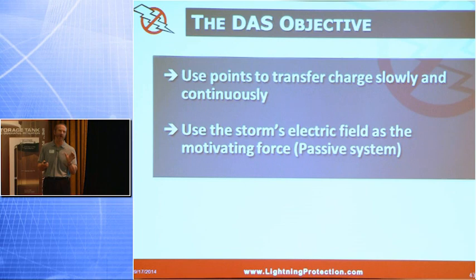You don't want to have too much attenuation. You want to have like 1 microamp full scale, because you're only going to use one nail, one point. Put it on a wooden pole, run it through that analog current meter and ground it, put a ground rod in, and have it maybe 5-6 feet in the air. And as a storm moves in, you're going to see that needle deflect. It's going to actually show that you're bleeding off current.